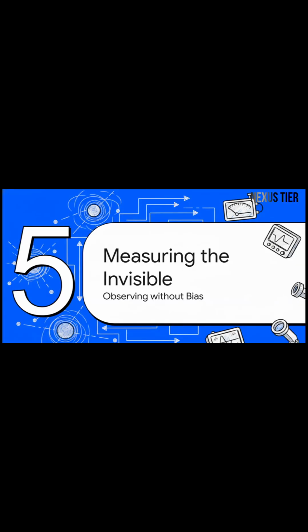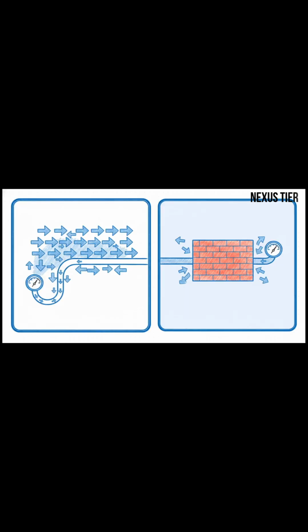And this brilliantly illustrates our final chapter, measuring the invisible. We're dealing with invisible forces and microscopic collisions here. So how do we actually observe and measure these values without breaking the very system we're trying to study? To do this, we use some incredibly clever external tools, usually built from a basic component called a galvanometer. To measure current, we create an ammeter by putting a very low resistance shunt in parallel. This safely bypasses most of the current right through the meter, without choking the circuit itself.